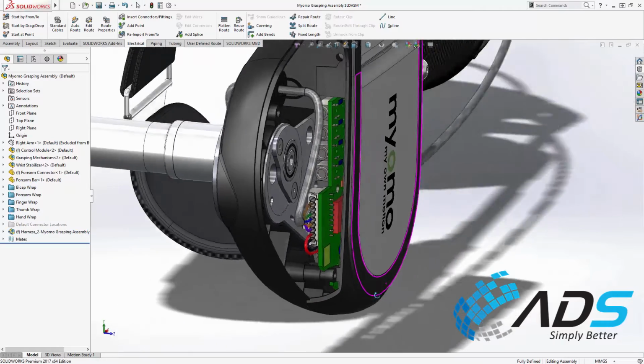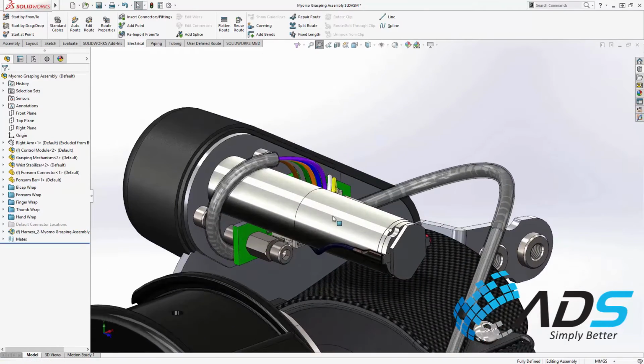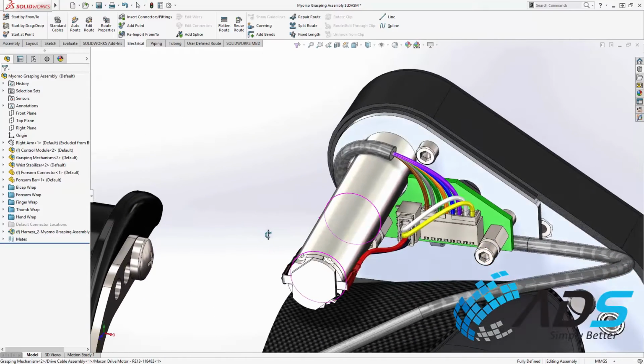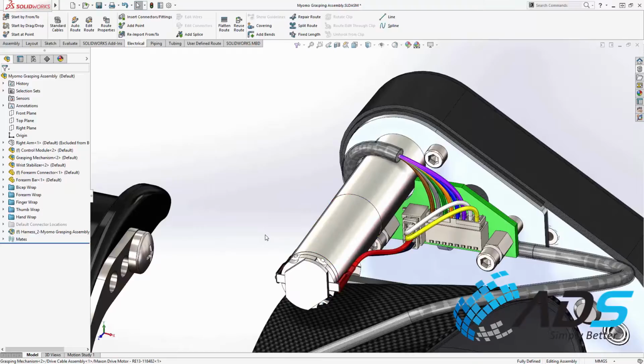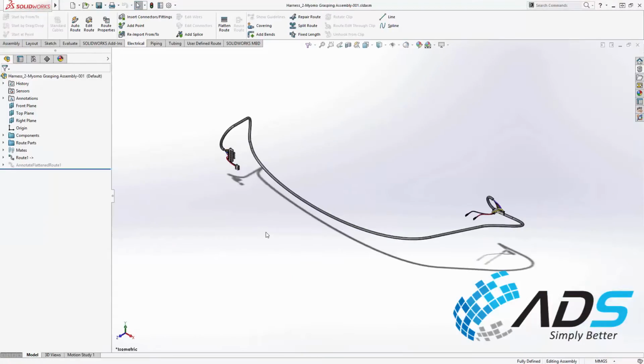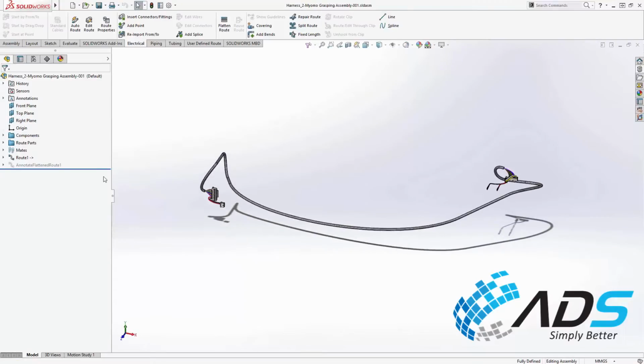Disjointed routes are routes which contain multiple or new route segments chained from one connector or a component to one another. These are different than branches within a harness. Previously, SOLIDWORKS routing would not be able to flatten these route types and would present an error upon trying to do so. SOLIDWORKS 2017 now supports the flattening of disjointed routes, allowing for more manufacturing scenarios.